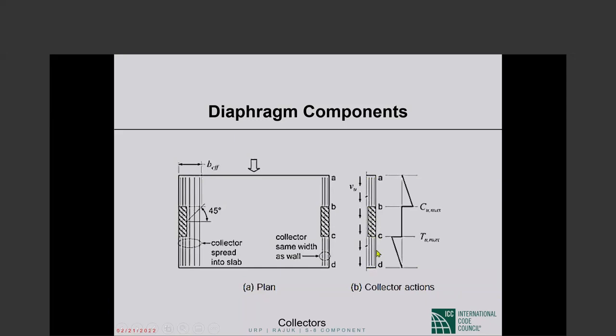Okay, so those elements are called collector elements or drag struts. They collect the shear force and deliver it to the resisting shear wall. Collector element. Okay, so we have to put reinforcing bars to carry the tension.